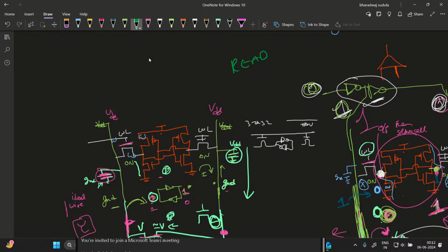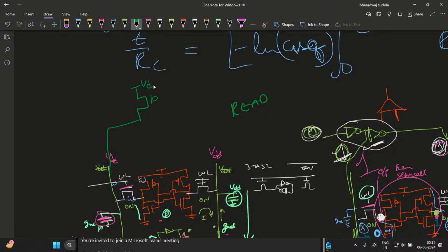So you just connect the bit lines to this PMOS, and this is VDD. Let's say I have given this control to a pin called PCHG. Whenever I lower this PCHG, the bit line recharges to VDD. And while reading, both the bit lines have to be at VDD, right? So simply I'll connect this to this PMOS itself.